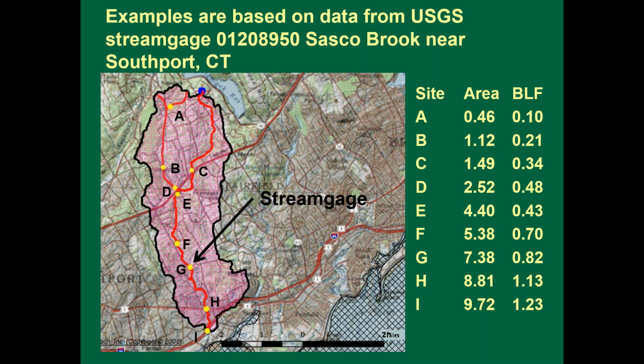The following examples are based on the assumption that the highway geometry remains the same, the basin area, length, and slope are variable, and the hydrologic and water quality data measured at the stream gauge are valid for the upstream and downstream points. So there are kind of 2 competing things: you're getting more storm flow for the whole storm, but the duration of concurrent flow may be going down because the upstream hydrograph is getting longer and longer, whereas the highway hydrograph duration remains the same.